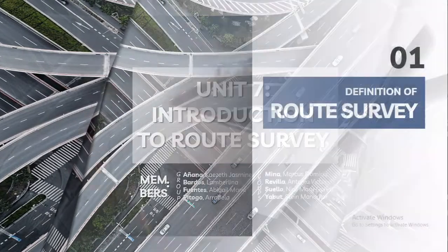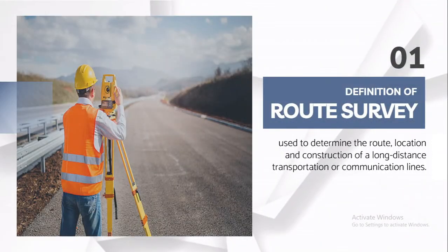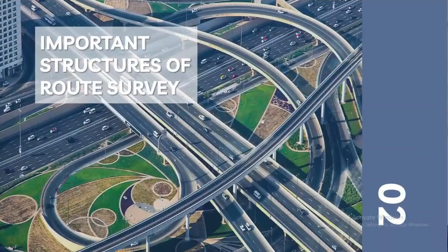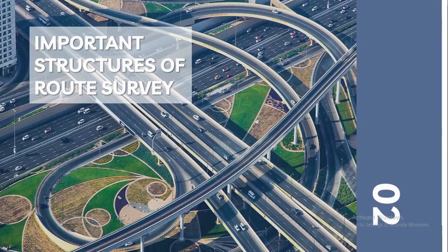A route survey is a survey used to determine the route, location, and construction of a long-distance transportation or communication line. It supplies data necessary to determine the alignment, grades, and earthworks quantities necessary for the location and construction of engineering projects. Important structures of route survey.